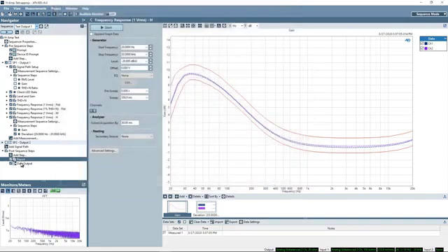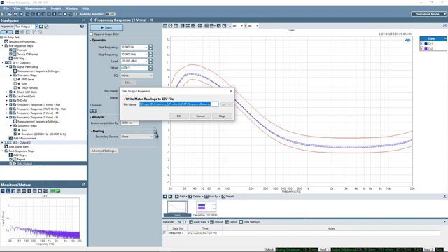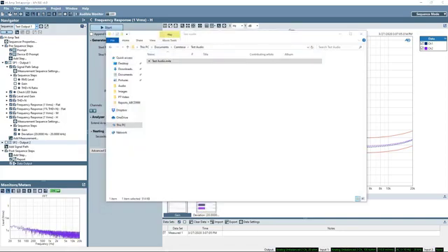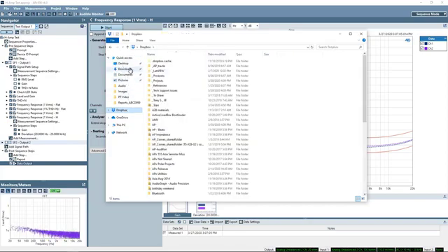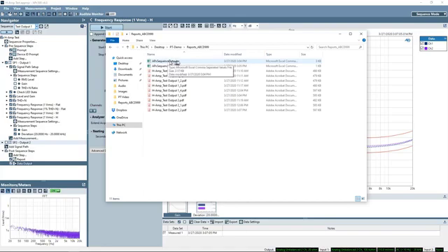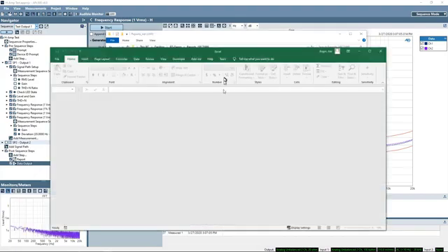This second node here is the data output node that we discussed earlier. The way this works is if you select its properties, using variables, you can specify, again, the folder where the sequence data.csv file is saved. Let's go in and look at that folder. It's on the desktop here, PT demo, and that's the name of the folder we created using variables. If we drill in here, we see the APX sequence data.csv, and this is essentially just a CSV file that we can open with Excel.